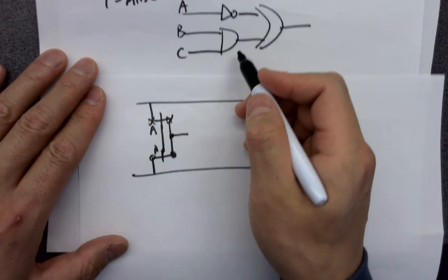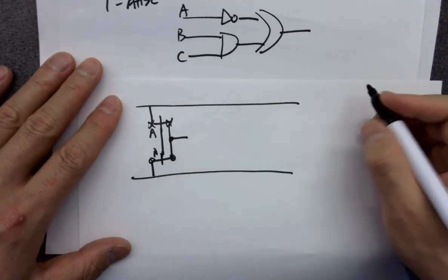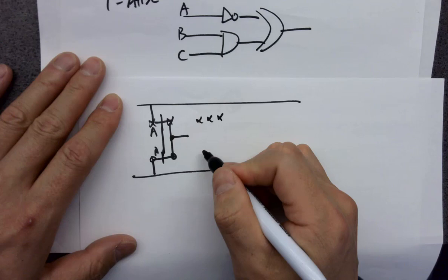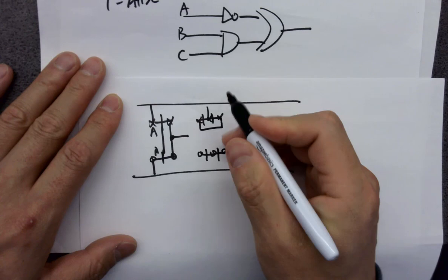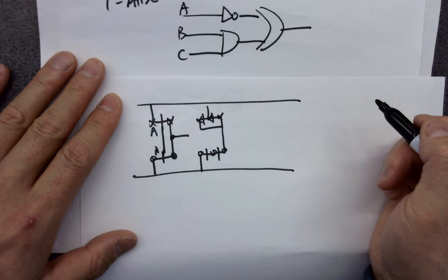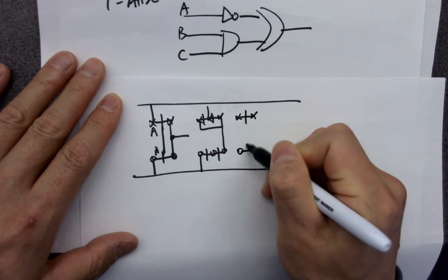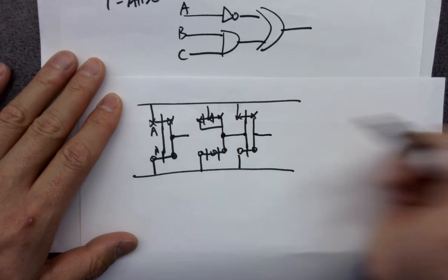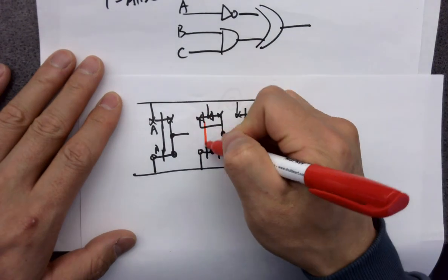And you need an AND gate. So AND gate, you need a NAND gate first and then invert it. So NAND gate has two PMOS on the top in parallel, and two NMOSes at the bottom in series. That's a NAND gate. And that needs to be inverted. So output goes to the input, and eventually that's the AND logic. Right? So these ones are the gates.